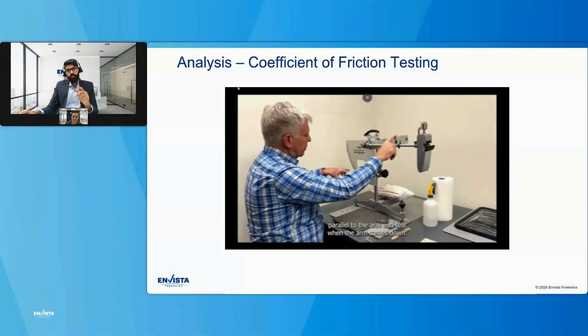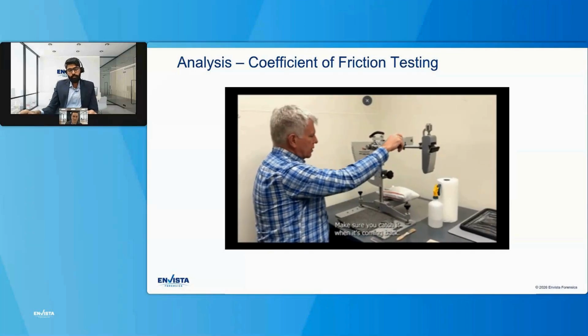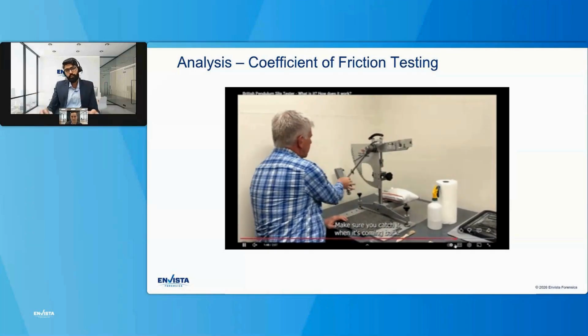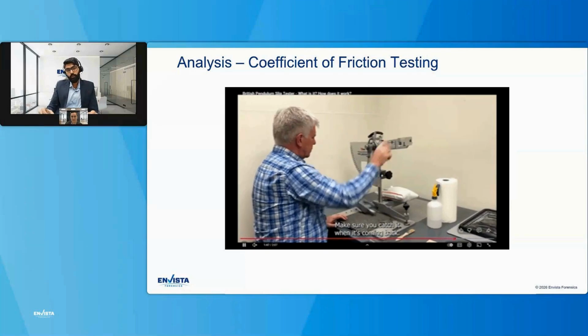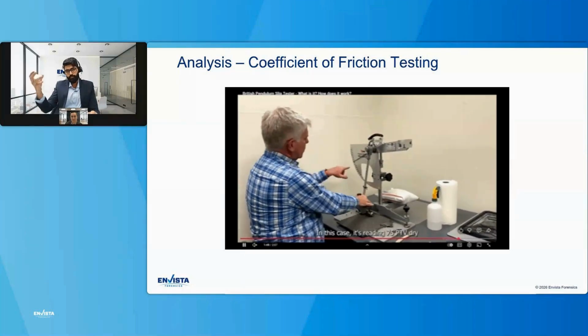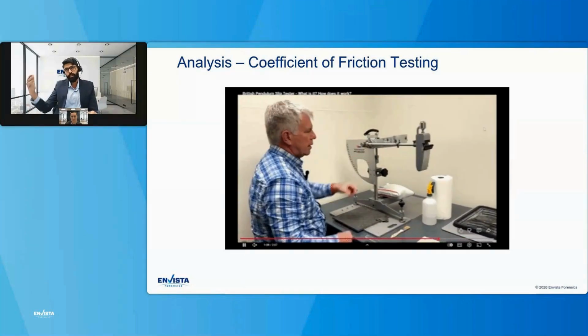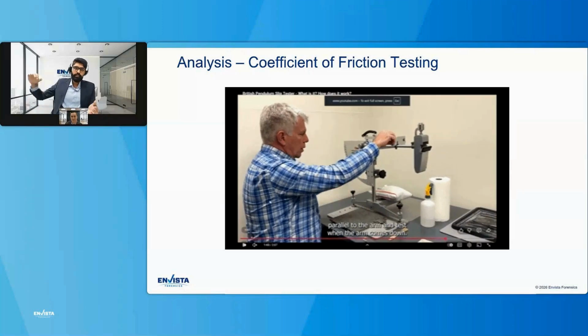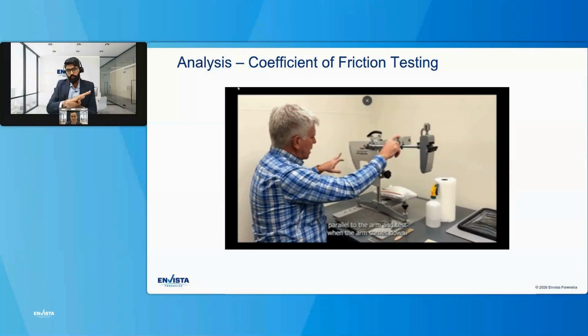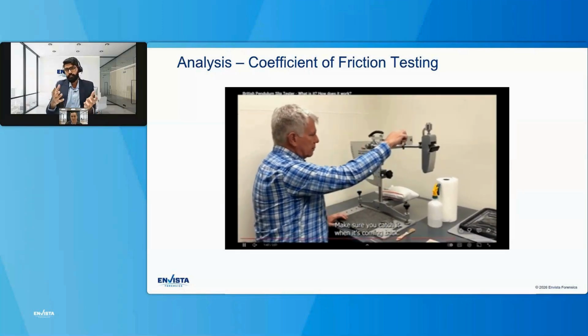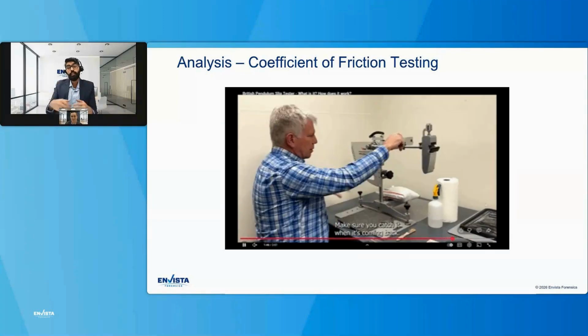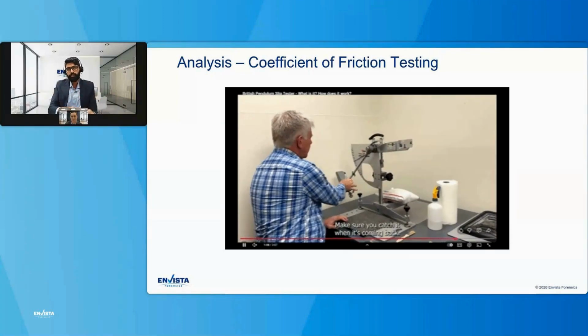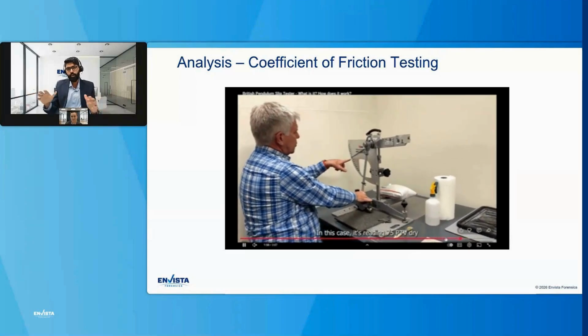Okay, the last equipment we will cover is the British pendulum. We all know how a pendulum works. Below the swing arm of this pendulum, there is a rubber sample attached, which is again supposed to represent your footwear. And as the pendulum is sliding over your floor, the amount of resistance it faces and has to overcome will be represented as your PTV value, your pendulum test value.